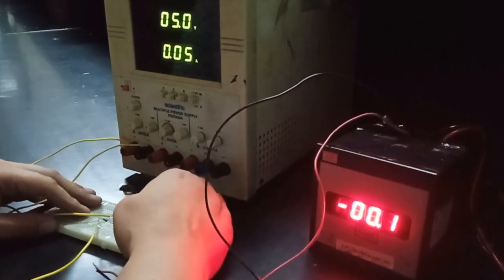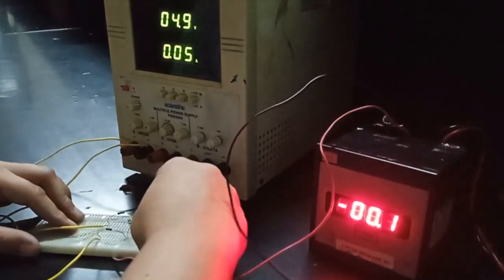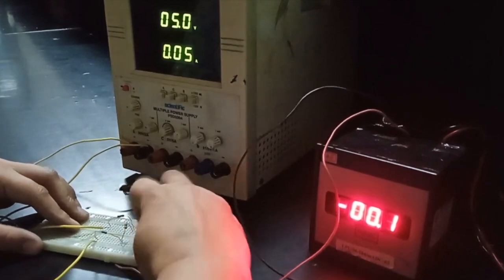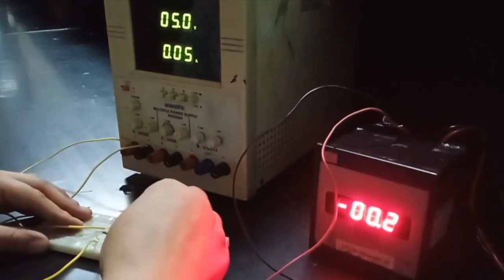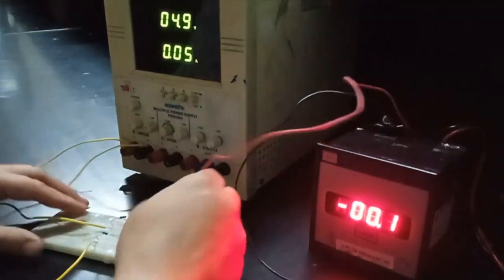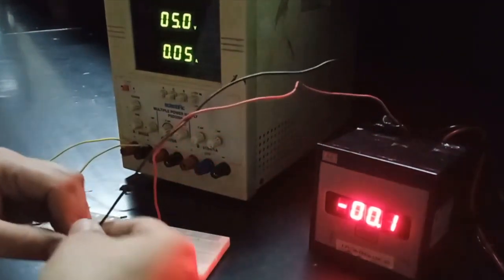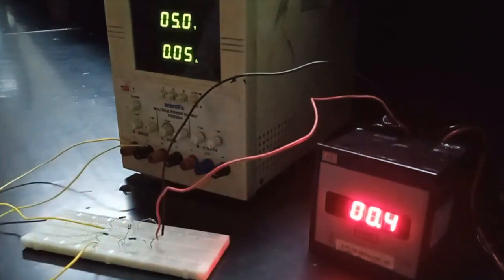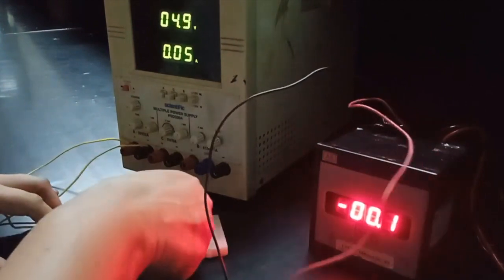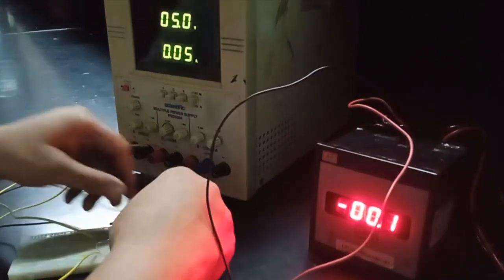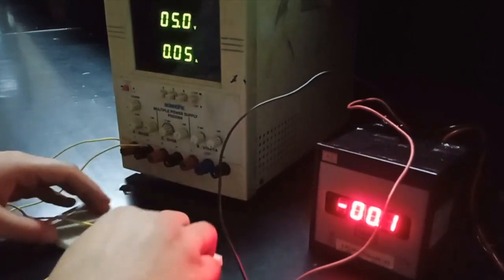Next, R4. For R4 restore the previous connection and remove one terminal of R4. So I have now removed one terminal of R4 so that we can connect the ammeter in series. So here comes the positive of the ammeter and the negative of the ammeter with the removed R4. So that also comes out to be equal to 0.5 milliampere. Restore the previous connection as it is. And now the final one,